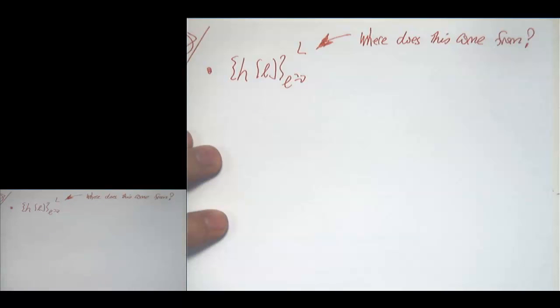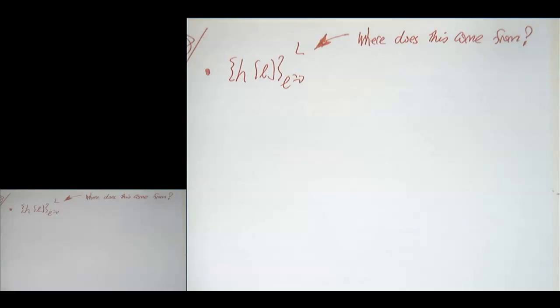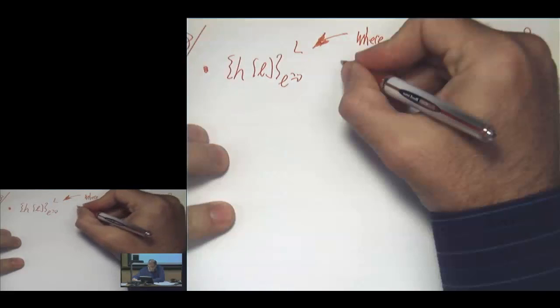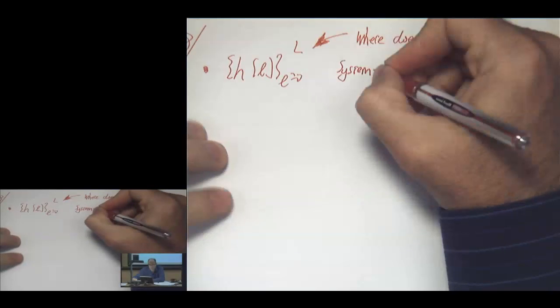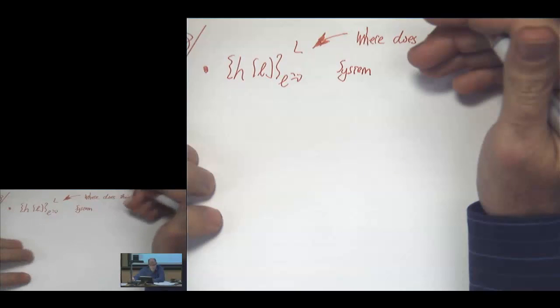The answer is going to depend on the propagation environment and measurements. The system is generally designed to operate at a certain set of carrier frequencies and certain bandwidths, and those will translate into different values of L for different environments. Downtown Austin will have a larger value of L than a rural place in, let's say, East Austin. So that will come from measurement data, and generally the system will be designed for a reasonably large value of L. You want to design it for an outlier case, not the average case.